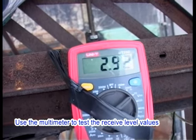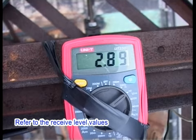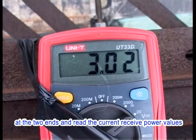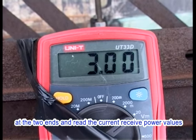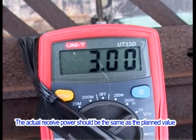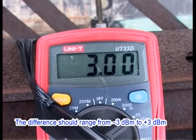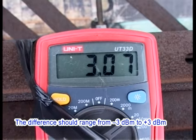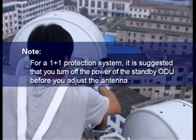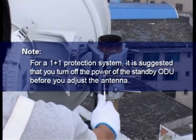Use the multimeter to test the receive level values at the two ends. Refer to the receive level values and the received signal level curves of the ODUs at the two ends and read the current receive power values. The actual receive power should be the same as the planned value. The difference should range from -3 dBm to +3 dBm. Note: for a 1+1 protection system, it is suggested that you turn off the power of the standby ODU before you adjust the antenna.